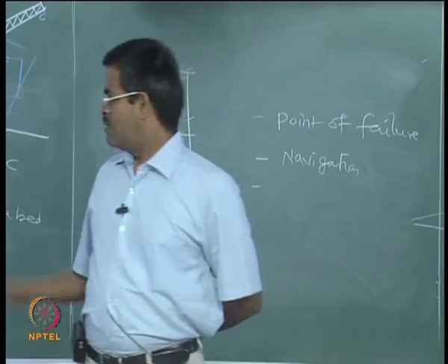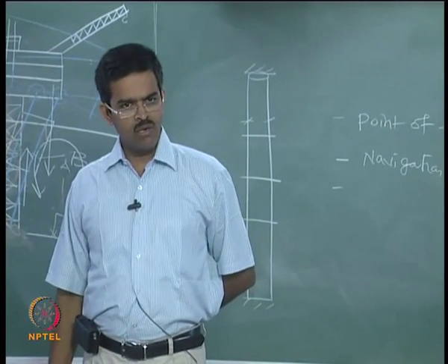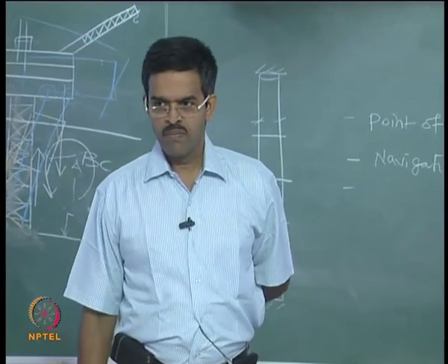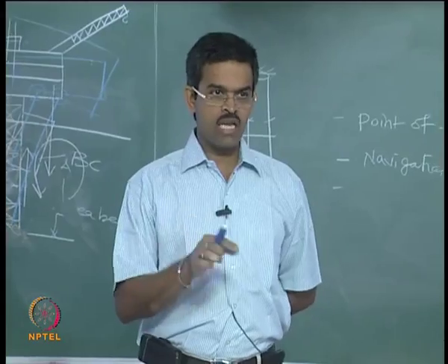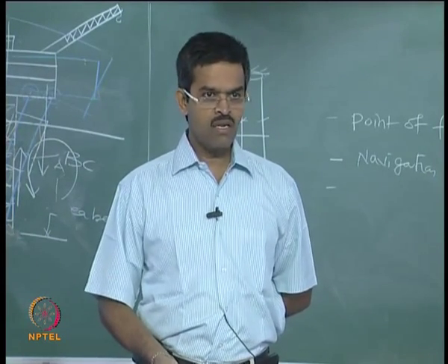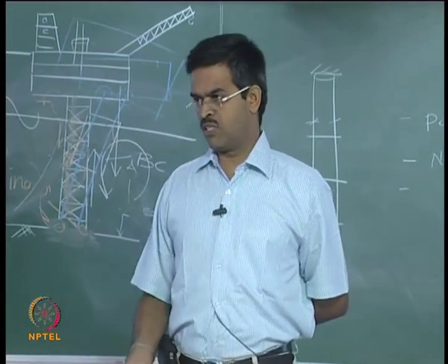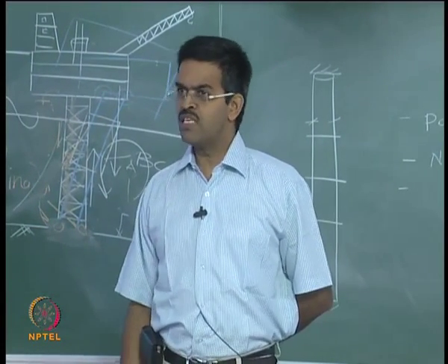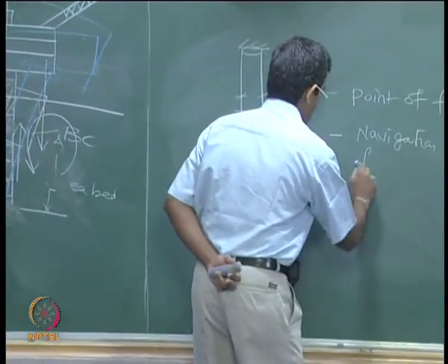Fatigue. Think about the mooring line tension forces. Will it remain constant all the time? No, it will keep on changing. So, any increase or decrease in axial tension is a reversal of cycle of forces, right. So, mooring lines will be subjected to extraordinary fatigue stresses, and that is dangerous, okay. Fatigue in mooring lines.